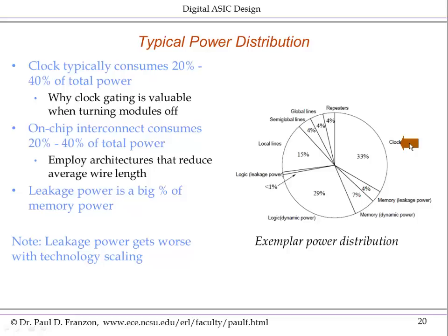So it has a fairly large capacitive load as well. Thus, the clock typically takes between 20 and 40% of the total power. Adding registers to a design not only increases the power consumption due to the internal operation of those flip-flops, but also adds to the clock load, increasing the power needed to distribute the clock.